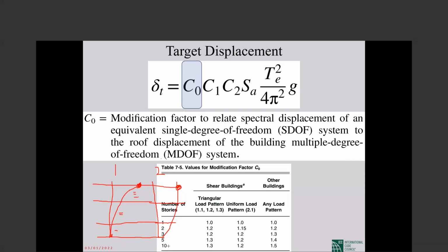So, for example, a shear wall system can't increase the stiffness in the upper stories because it's a bending type system. A bracing system can't increase the stiffness at the top. If you want to increase the stiffness, it is at the bottom.